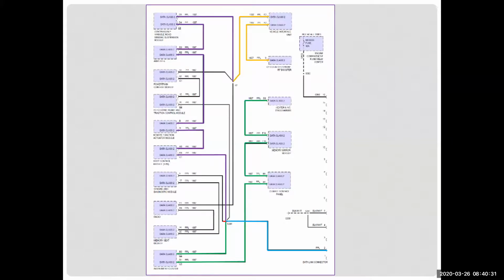And a lot of times the codes don't tell me which way I couldn't get there or where the problem was. They just say there's a problem. And so many times those codes are ignored. So even though we clear them, they come right back, all the modules are working and the car has no drivability fault. Normally we don't fix those because A, the customer doesn't want to pay the money for us to find something that they're experiencing no issue with, and those codes will not turn on the check engine light, so it's not going to interfere with getting a smog. That'll only create a problem when you get the second fault, and now the system doesn't communicate because we have two broken wires in the same network.